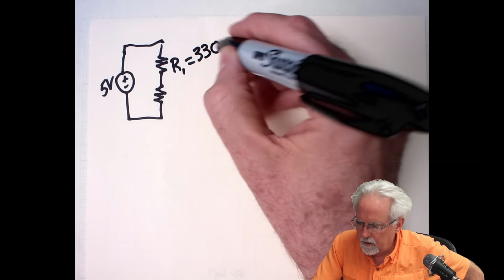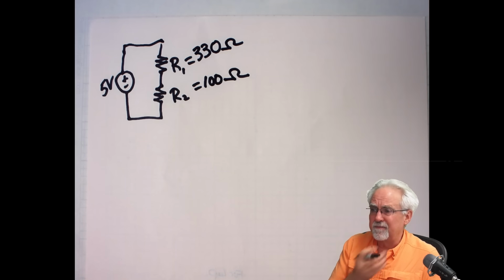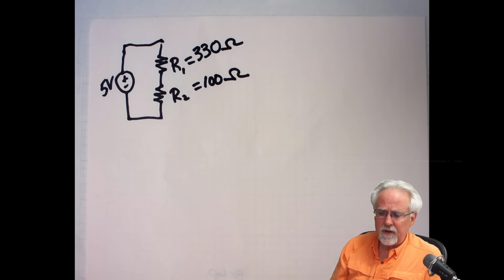Now, if you think of Ohm's law saying V is equal to I times R, well, you've got 2 R's here. Well, the thing that you have to understand is if there's only one path through the circuit, if everything is in series, it becomes very, very easy. If it splits, if the current branches into 2 paths, then you've got to do some more complicated stuff. But most of the stuff that we're doing, it's in series like this, and so you can do it this way. This is how you deal with resistors in series.